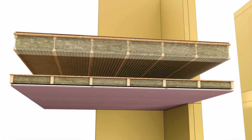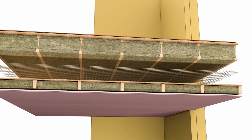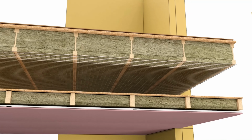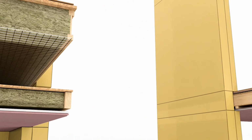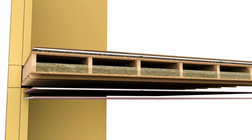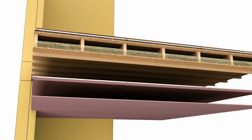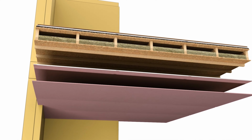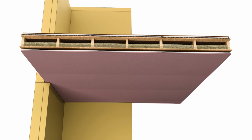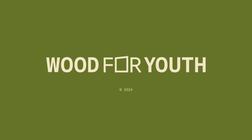For modular buildings, a metal mesh or wood-based board is typically installed on the floor panel to support the mineral wool between the beams. In element buildings, the lower layers are made up of battens. Depending on the project and the size of the intermediate floor element, the board layers that form the ceiling of the lower floor can be added either in the factory or after the element building has been erected.